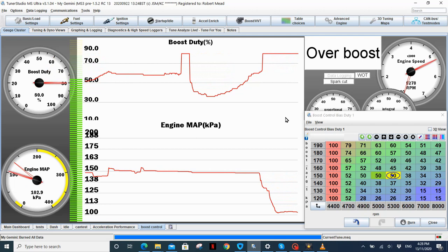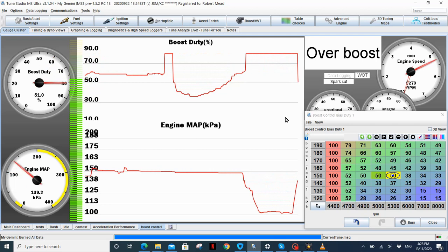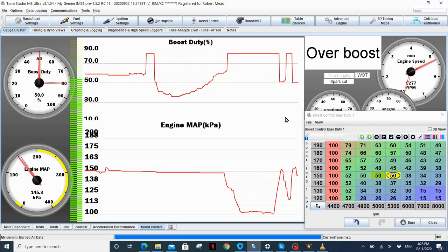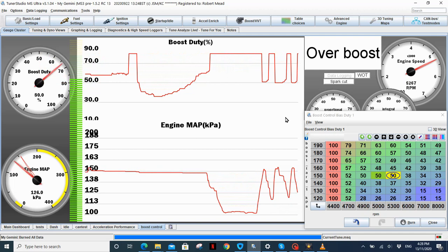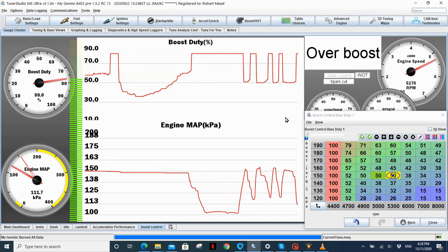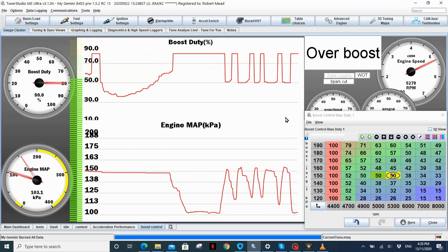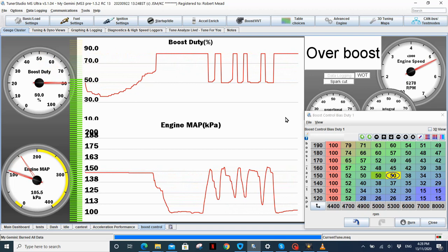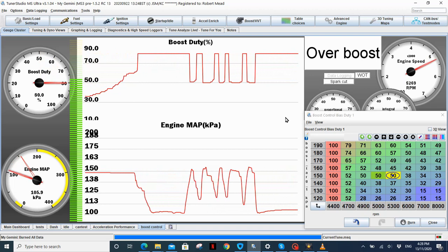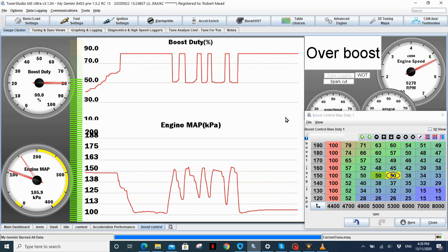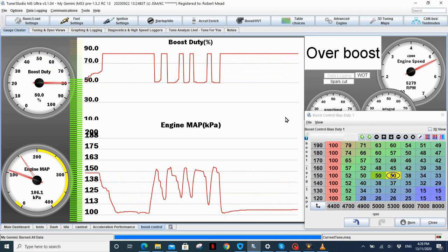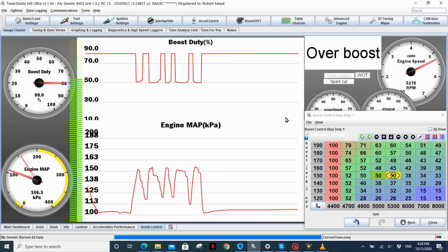That's another reason why you want that delta tight. If you drop it, boost down, like you get off the throttle momentarily, you can pop straight up and it will reset that value. So if the PID's run away from you, it'll reset that and bring it back to where it should be if you've got that bias table set up properly, right?